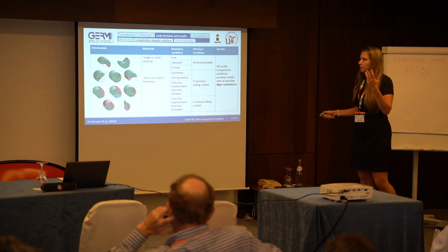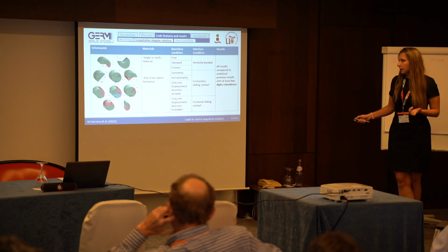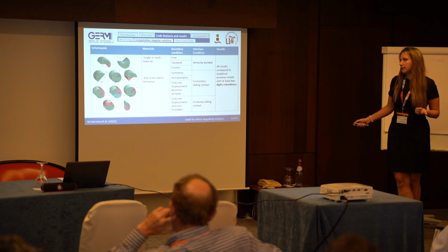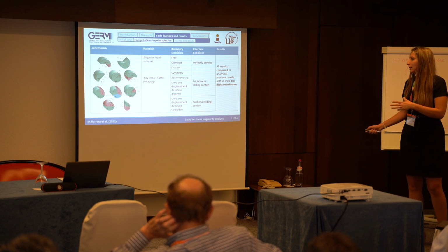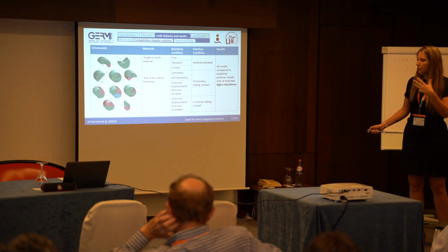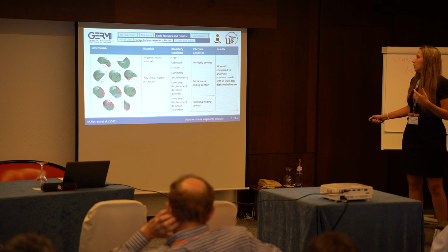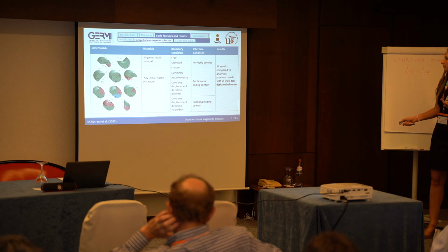As we said at the beginning, the goal of this code is to be more general than all the others that were already done. So we can solve singular multimaterial problems with linear elastic behavior for boundary conditions free, clamped, friction, symmetry, antisymmetry, only one displacement direction, or only one direction of sliding forbidden, with interface conditions perpendicular, frictionless, or frictional.